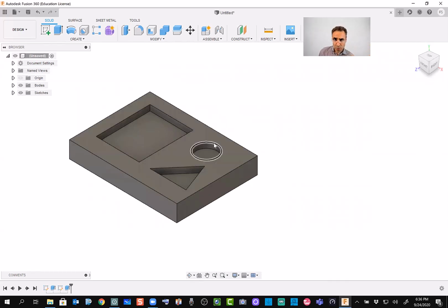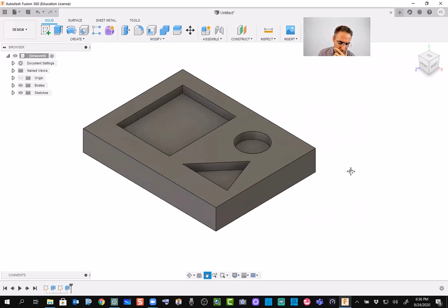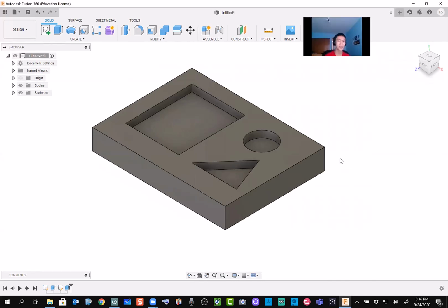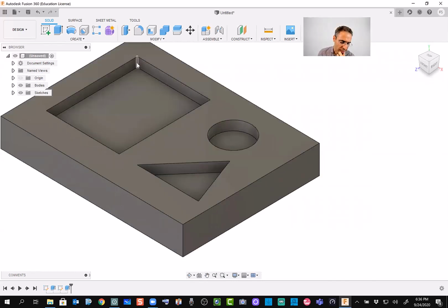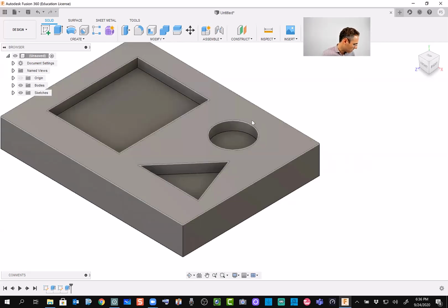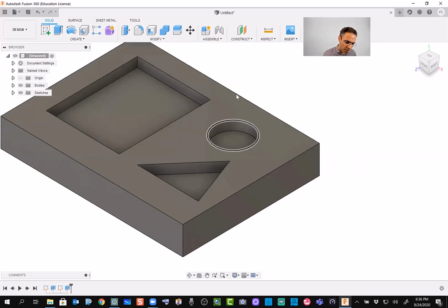Now it's time to do a milling for this one, but do you guys think that we can machine this one down and create these pockets? It's okay to do that? You need fillets. Great, yeah. This sharp corner, we cannot really machine that and create those. Our tool is going to say, sorry, I cannot do anything for you. So, as Jesse pointed out, we need a fillet.